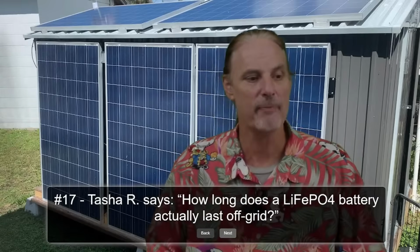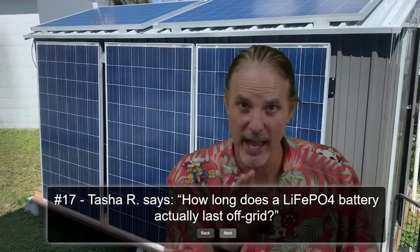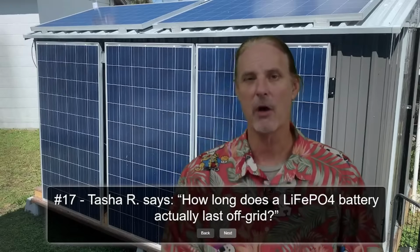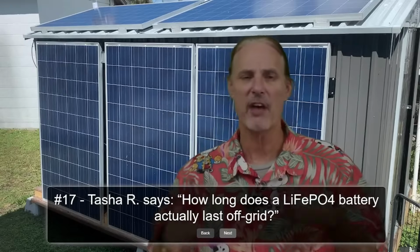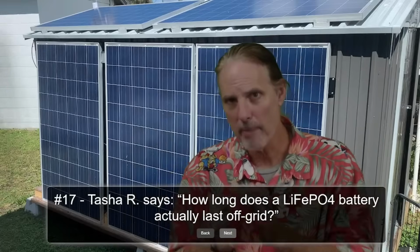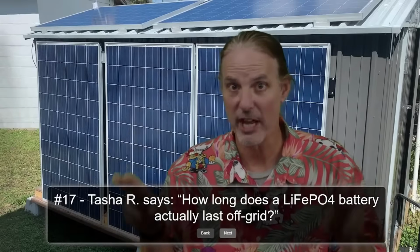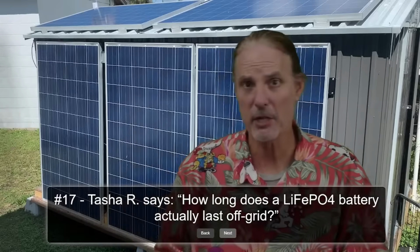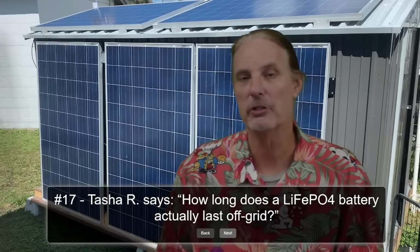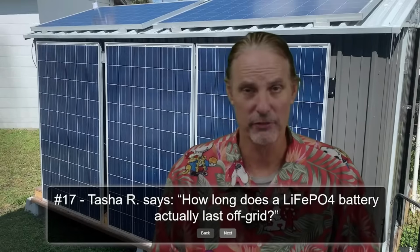How long does a LifePO4 battery actually last is the question, and I'm going to get to it, but I wanted to go over how it related to state of charge first. Most of the batteries that are coming out claim to have 5,000, 6,000, 10,000, 12,000 cycles. The problem with this number is that nobody has defined what cycles mean. And every manufacturer defines it differently. And most of the time you don't know until you start reading the actual manufacturer definition of cycles.